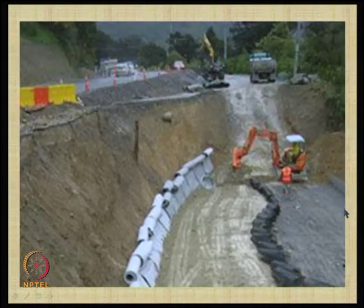See what happens: water comes here, and that should not create a shear failure here. So, all the water should go through these prefabricated vertical drains, that is how the drains are installed here. This is another application, not a consolidation type. PVDs in fact have been used behind retaining walls also to increase the rate of drainage.